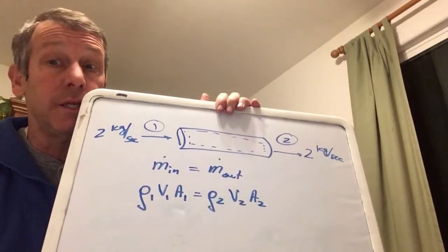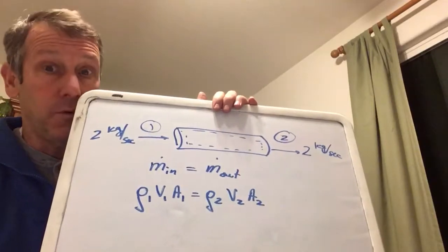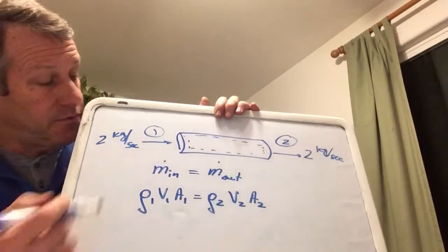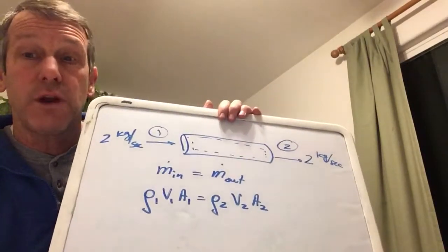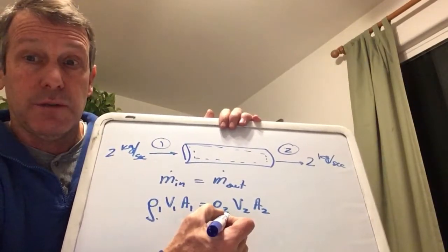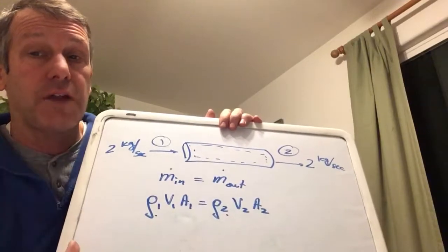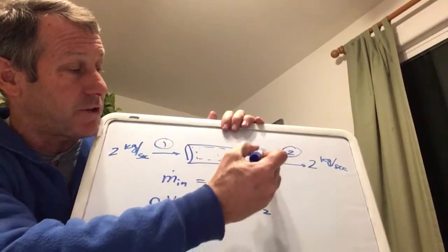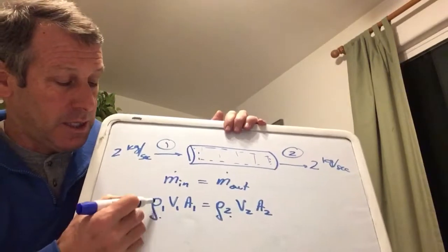with something really easy. Let's see what that equation says for a fluid entering a pipe and the fluid's incompressible. So I have some fluid entering the pipe and it exits the pipe. If it's incompressible, that means the density at the entrance and the density at the exit would need to be the same. Okay? If it's a pipe of constant cross-sectional diameter, the cross-sectional area is the same, this area and this area would be the same. And let's see what that says.